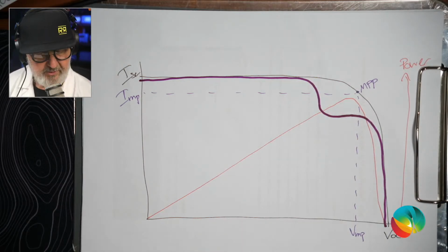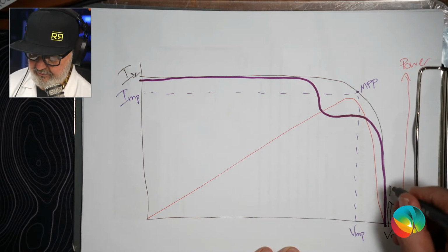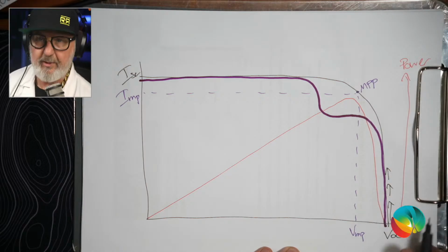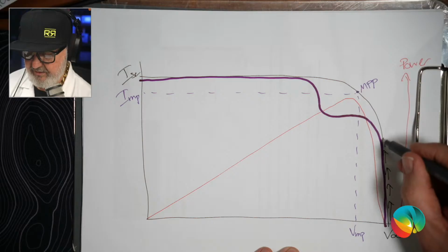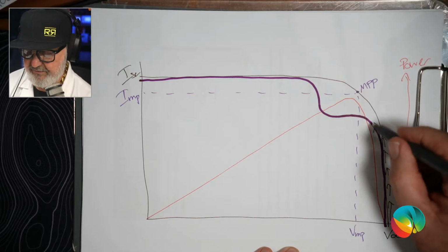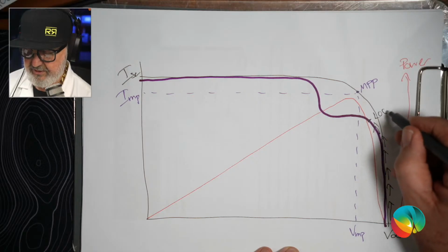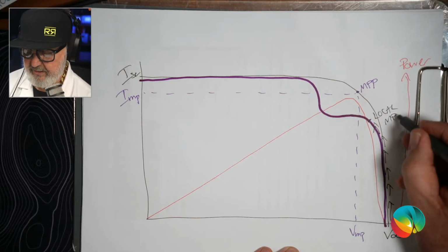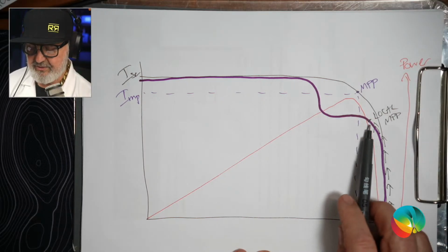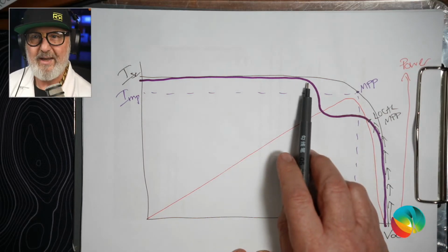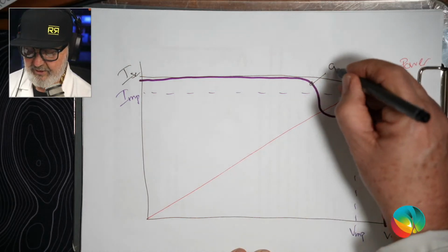And remember I told you that a maximum power point tracker starts by going along from open circuit voltage, trying to find the sum of volts and current being the greatest, and it'll get to the first bump and it'll go, I found it. So we call this the local maximum power point. And it stops there. But it might turn out that actually that other one gives you more power, but it never gets there. So this one we call the global